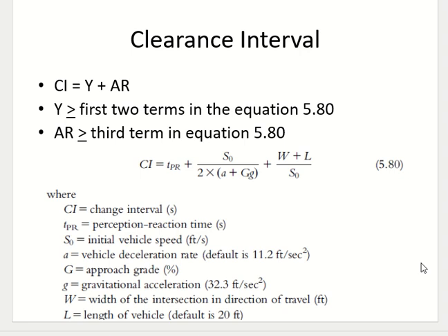So all red is calculated for a vehicle to cross the entire intersection and reach the other side completely, with nothing left behind. This one is the time the driver needs to stop at the stop line, and this one is the time the driver needs from the stop line to reach the other side completely safely. So this is the yellow and this is the all red. Clear? As you can see, this is fixed according to the dimensions, the speed, or the design of the road. Any questions? We'll discuss the rest of the steps tomorrow.